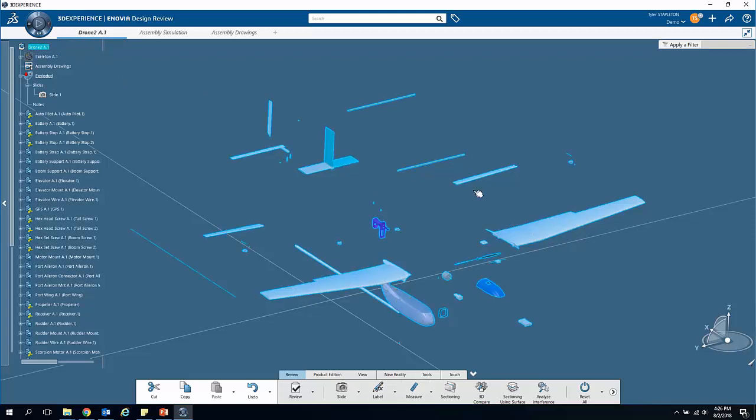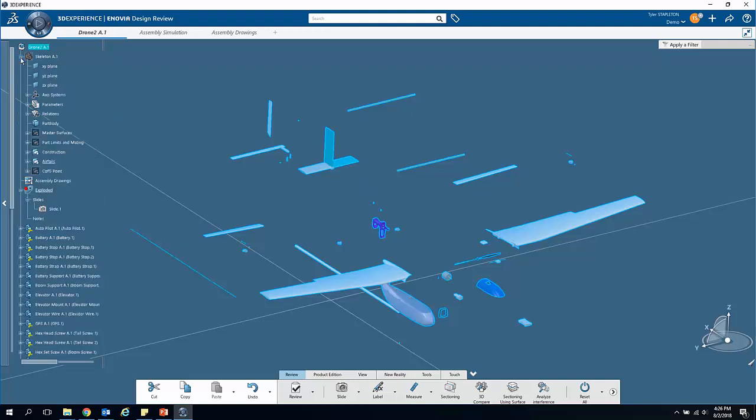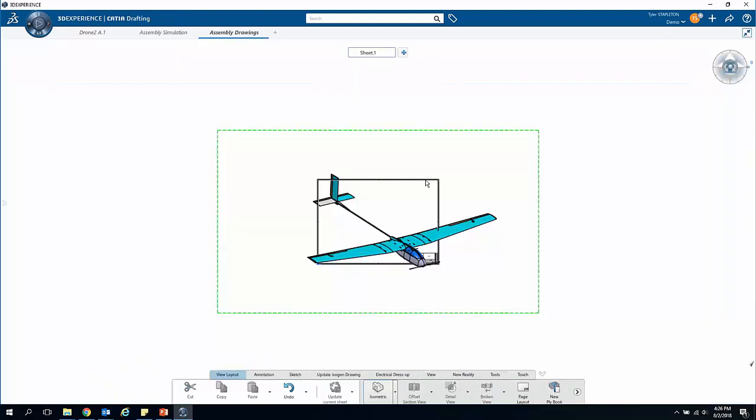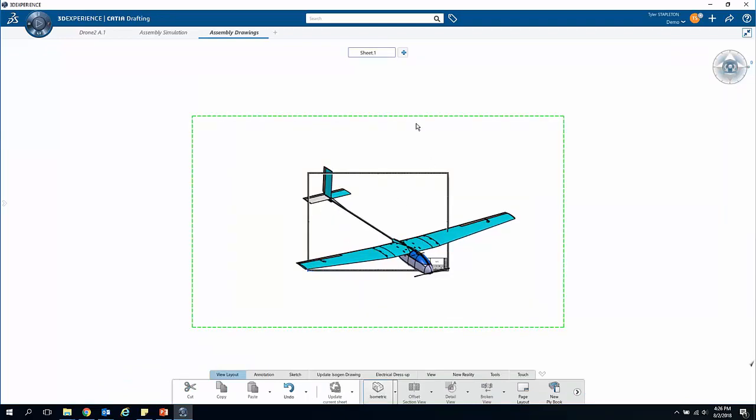And now what it needs is it just needs a plane so that it knows what set of planes I'm using as my central set for this model. So I'm going to come into my wireframe, here it's called skeleton, and just select one of those planes, and it's going to create that view. Alright, first thing that you should notice is it's wrong. It's the assembled view, and that's not exactly what we were going for, but that is still the process of creating this. And the reason why is because I didn't use that slide that I had placed within the markup.